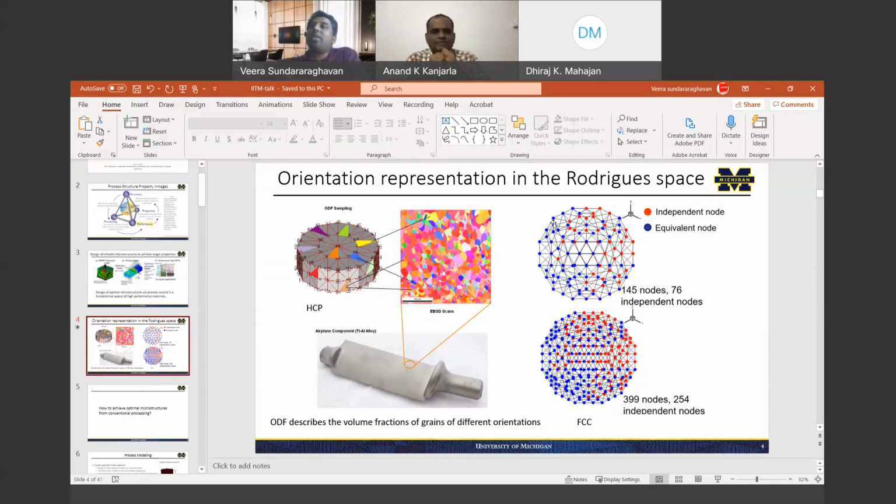Unlike Fourier, where you cannot get these sharp textures unless you have lots of coefficients, in the finite element space you can do very fine textures, because I can have a node with very high intensity. With a single crystal, basically, you have only one node with a delta function. That can be done, but to answer your question in a more refined way, you can always start with a very fine discretization. You assume that it captures sharp textures that you can get from certain processes.